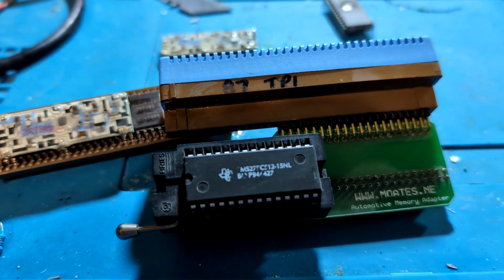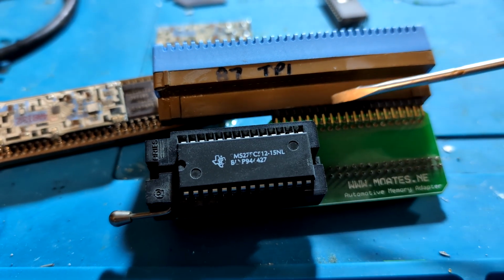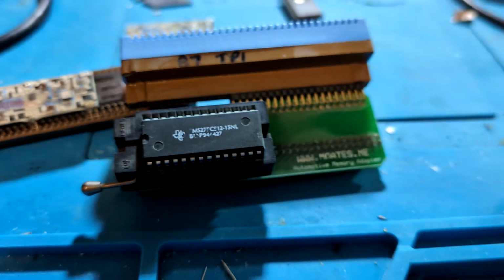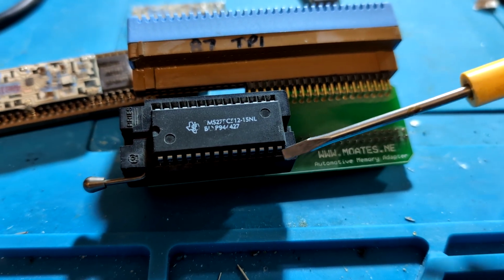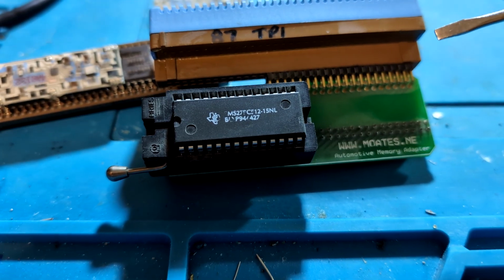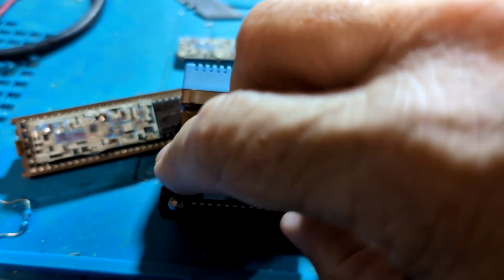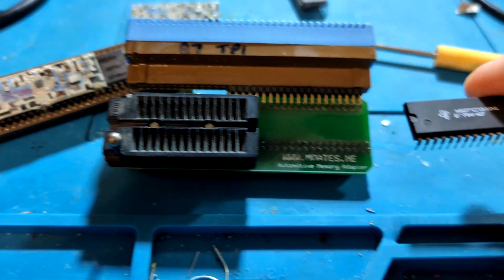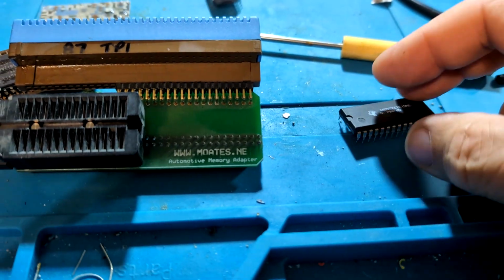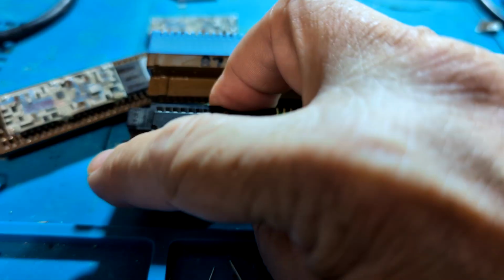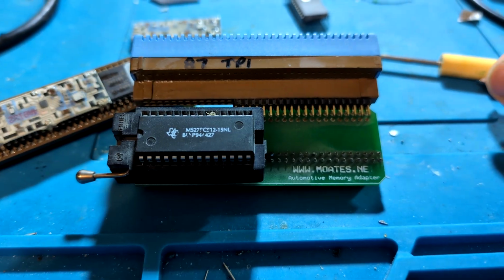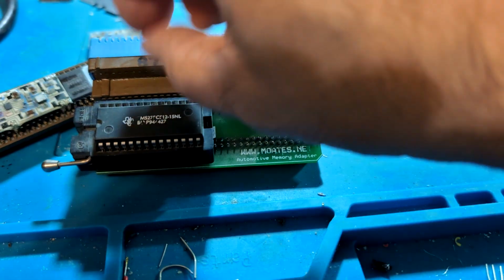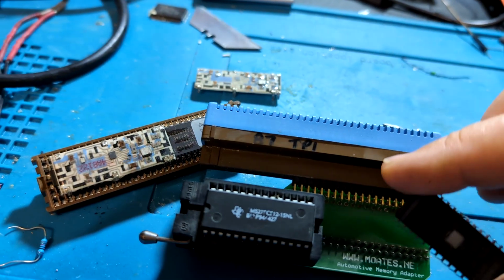But what this allows you to do is essentially, it allows you to use an EEPROM in a removable ZIF socket. So the way that works is you just lift up that lever, then you can take your chip out, take it over to your EEPROM burner, burn the new program on there, then bring it back over here, drop it in there, flip that over, and then you're good. So obviously much easier than trying to burn one of these things.